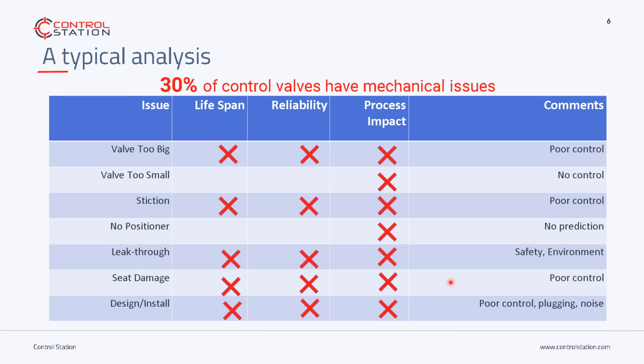Plus, if the proper effort wasn't applied up front for the design and installation of the valve, which I have encountered a lot in my industry career, you're going to end up with issues ranging from poor control to plugging, and the issues I just mentioned with erosion and corrosion. I feel from my experience that in most cases there has not been the proper emphasis placed on upfront design.